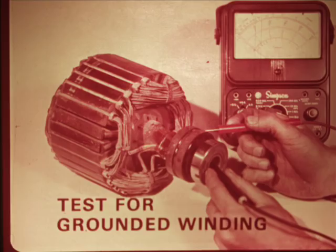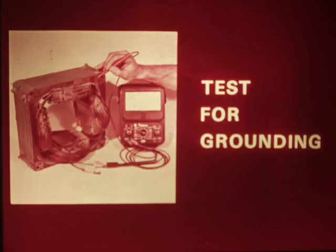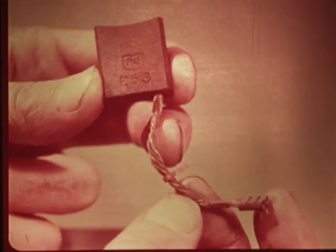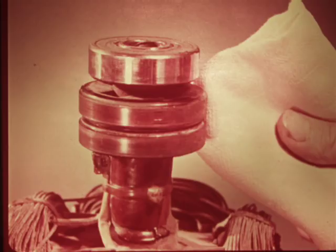Let's summarize. Most problems in the generator will probably be caused by the rectifier or the compounding reactor. But while you've got the generator apart, check it out fully. Test the armature for grounded and open windings with an ohmmeter or a powered test light. Also, test the field windings for an open circuit or grounding to the housing, and be sure the wire terminals are tight. Check the bridge rectifier by testing each of the 4 diodes for low resistance one way and infinite resistance the other way. Check the brushes for excessive wear, and be sure their wires are in good shape. Always replace brushes in sets. Clean the slip rings with a dry, lint-free cloth and remove any roughness by light sanding.